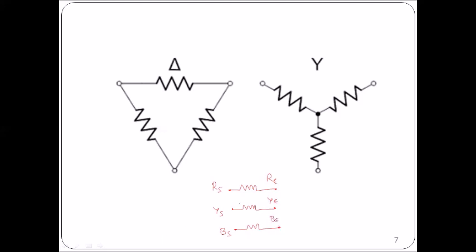So in the case of star connection, we just connect the endpoints. Whenever we connect the endpoints, power supply is applied to the starting points. We apply the electrical power supply to the starting points, and the endpoints are connected together. It is called a star connection.